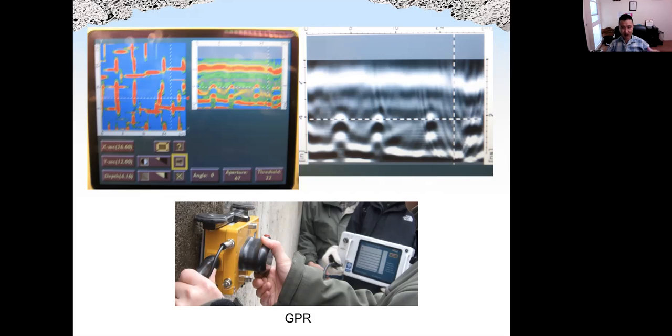So the GPR can give us almost a 3D, we call that 2.5 dimensional map of reinforcement beneath the concrete. We run the GPR in layers, different lines, horizontally and also vertically, all along the surface. The instrument will generate a 2.5D map or drawings for the rebar. Like we can see from here, the red lines are rebars.